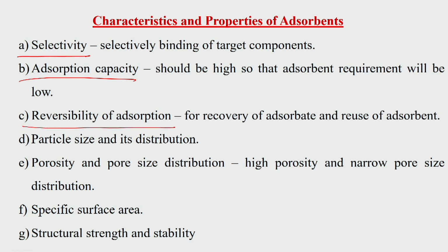This is called the desorption process. We will be discussing this in detail also, for recovery of the adsorbate and reuse of the adsorbent. Whenever we trap an adsorbate from a mixture, how easily can we separate it from the adsorbent? If there is very good compatibility and the adsorbent is not ready to release the adsorbate, then the adsorption process may not be economic, because once it is trapped, it should also be separated very easily by applying different techniques.